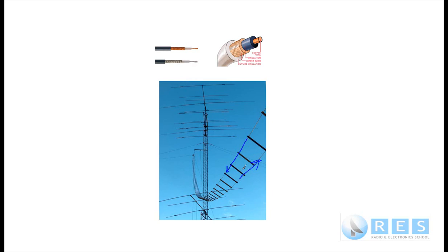Remember the old TV antennas? They used to be up on a metal pipe, and they would put standoffs away from the metal pipe, because if you put the parallel line near the metal pipe, one side of the line will have more capacitance between it and the pipe than the other side of the line, and it would be unbalanced. So the parallel line was fed up through standoffs and then connected to the antenna. Parallel line is very, very good low loss line.